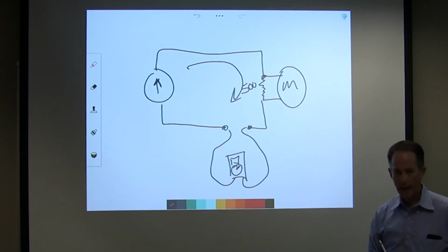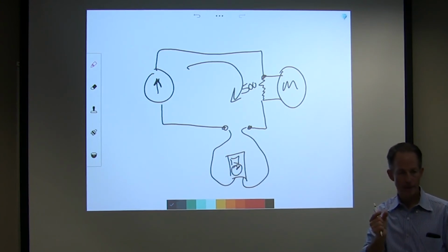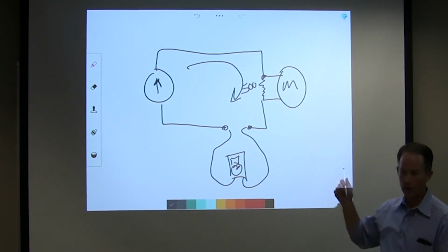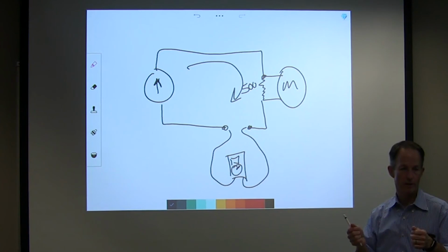And so what happens if I put a teeny tiny resistor in there with a big voltage? Yeah, it blows the fuse. You can get a lot of current flowing, right? So that's why you've got to be careful on how you hook this up. You can't just take a milliamp setting on an amp circuit, because it will pop the fuse. It doesn't take much.